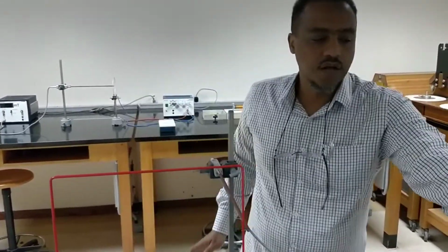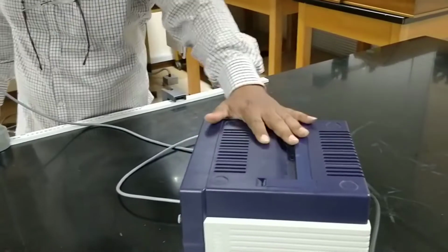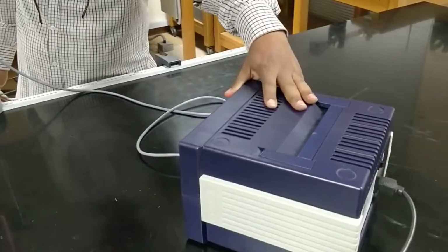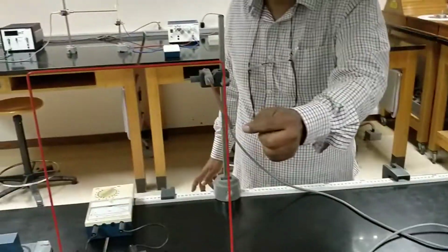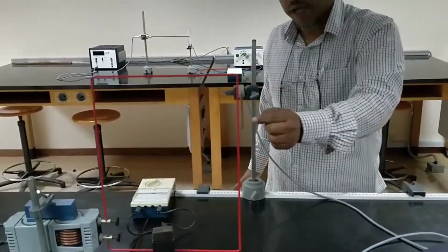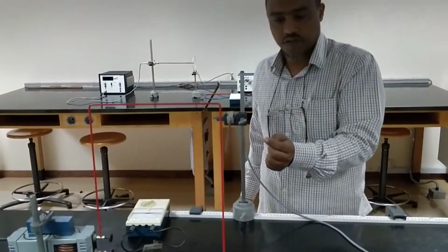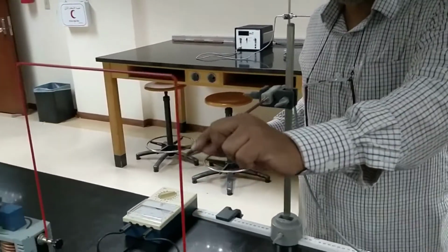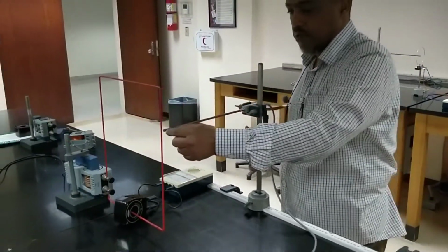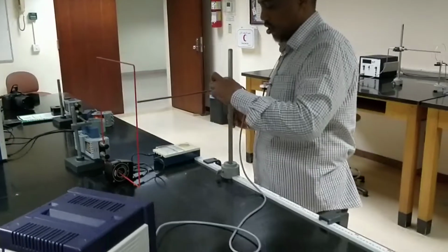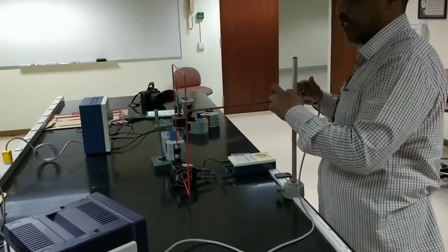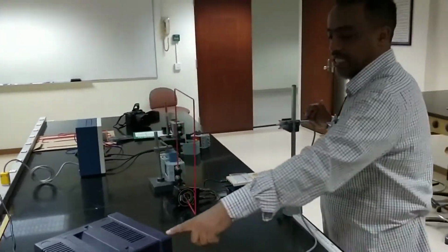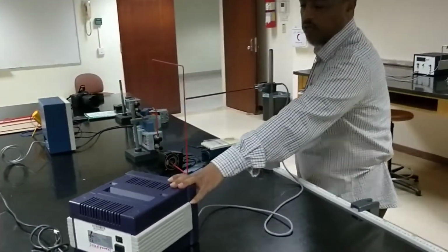and we call this one a Tesla meter. It measures the magnetic field at the tip of this probe, and that is parallel to the probe that we have here. Because of this, we call this probe an axial probe. It measures parallel to the axis at the tip. If it is parallel toward the direction of our probe, then it is positive. If it is opposite, then it will be a negative value, and it is displayed on the screen that we have here in our Tesla meter.